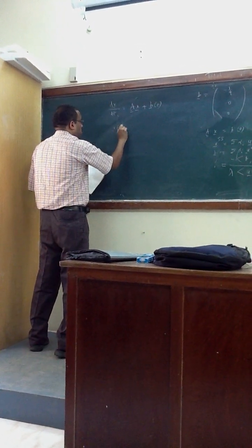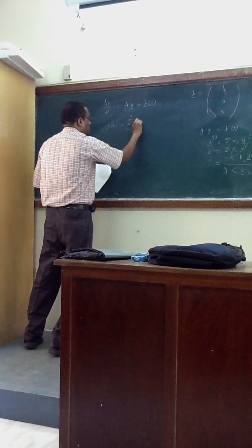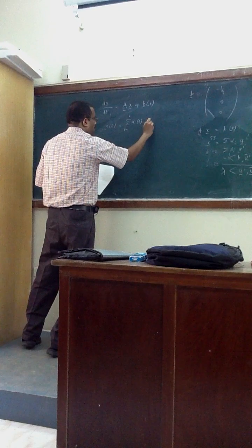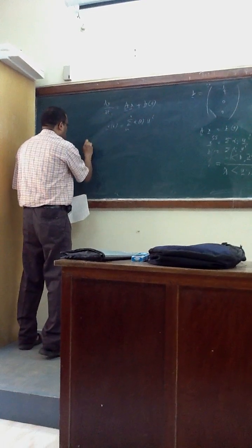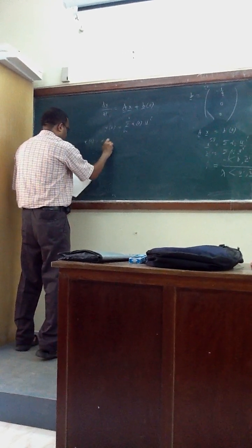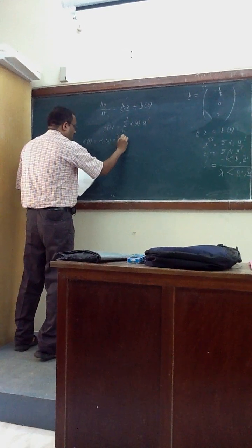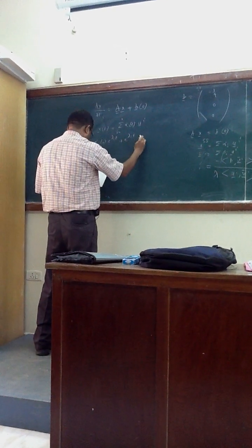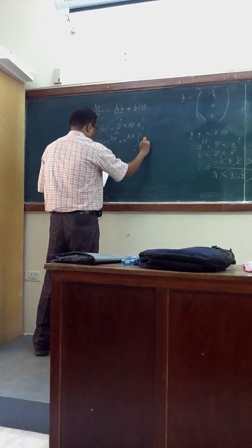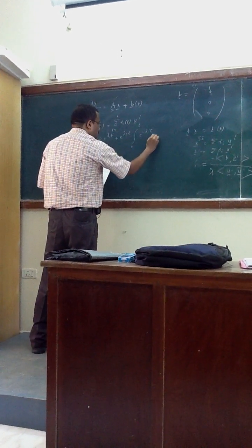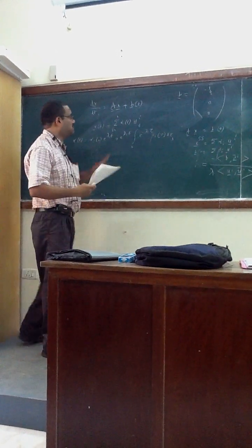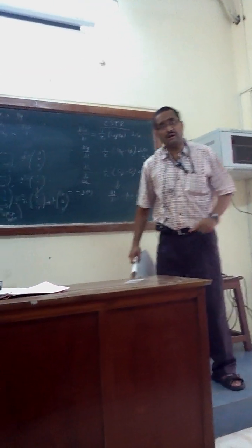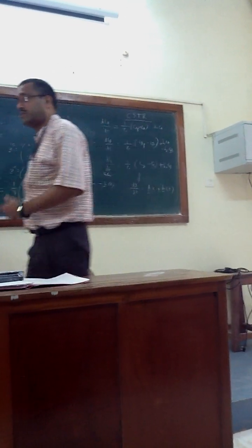The solution is x(t) equals the summation i equals 1 to n of alpha i(t) u_i bar, and our matrix is non-symmetric. We got alpha i(t) in terms of alpha i(0) e to the power lambda i t plus e to the power lambda i t times the integral from 0 to t of e to the power minus lambda i tau beta i tau d tau. By beta i, you know that b is the summation of beta i u_i bar, and beta i can be obtained using the orthogonality criteria, or the bi-orthogonality criteria for the complex conjugate system.